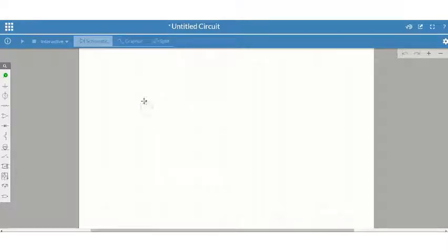Once you have placed it, you are able to move it around. So if you find later that where you put it was inconvenient, not a huge deal. You can totally move that around. A couple of other things to note. Every element that you put into your circuit is going to be labeled with a name. So this has a name V1. And then it also gives you some information. So this is a 1 volt energy source, and it is alternating at 1 kilohertz or 1,000 times per second.